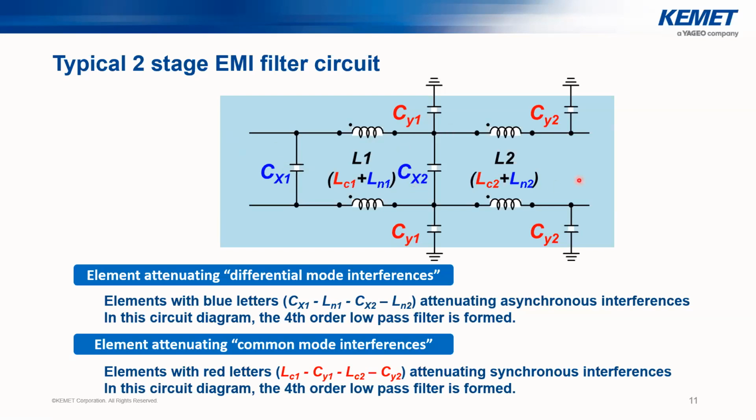Usually you would have a differential mode choke and a common mode choke separately. But if you see this figure, I have actually included the differential mode behavior as well as the common mode behavior within a single choke. Now, how might that be the case? Because usually you would come across two different sorts of chokes. Well, this would be the first basic passive element that I would be addressing in this presentation today.